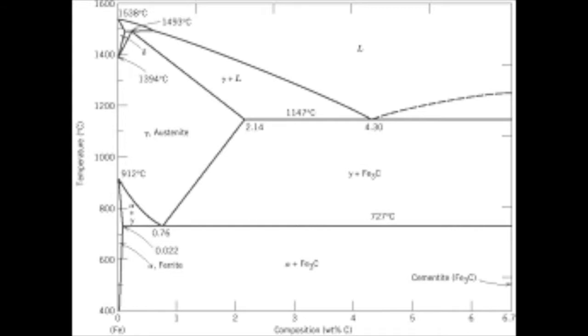To alleviate these stresses, we chose to stress relieve the shackle by heating it to approximately 650 degrees Celsius for 1 hour, which is just below the A1 eutectoid line for an iron-carbon phase diagram. This ensures that no phase transformation will occur, but that the stresses can still be relieved. The legs would then be bent to the desired width in preparation for the next heat treatment process we chose,